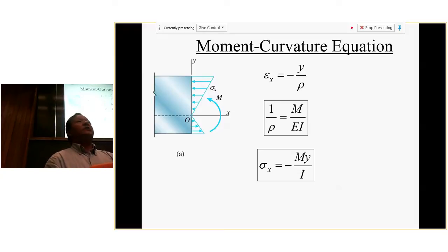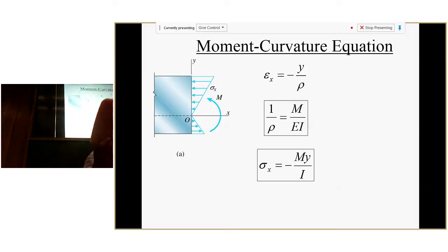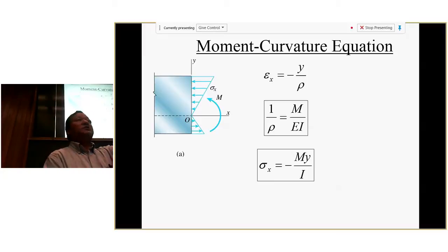So today we're going to continue along this line, and talk about how to find the maximum stress, because that's what we care about, right? Where is the failure going to occur? How much can you load the beam when you design a structure using a beam? Or it can be, for biomedical engineering, a piece of bone, or a piece of artery, or a piece of muscle, right? Anything in the body under bending, how do you determine where the maximum stress is? Because everything in the body, when you move around, there will be bending as well.